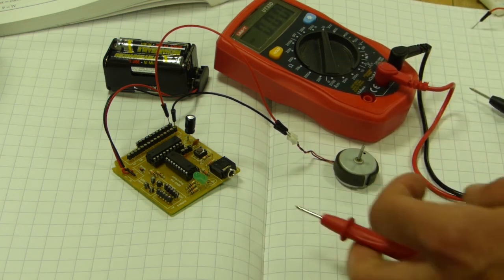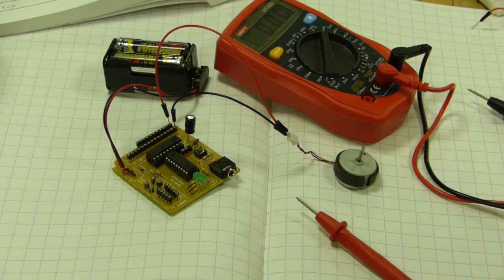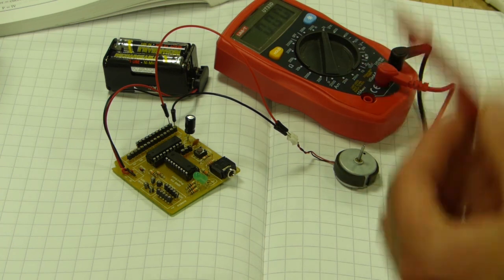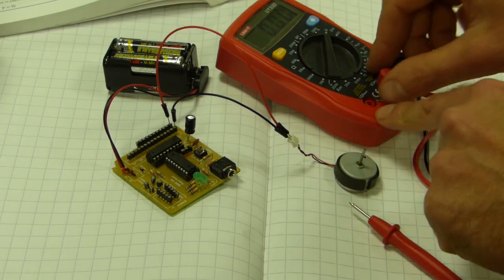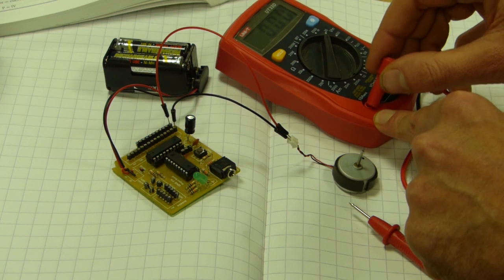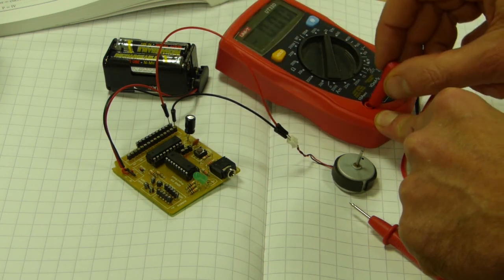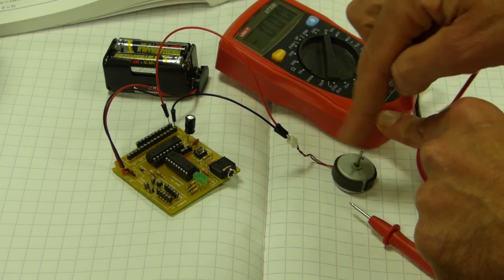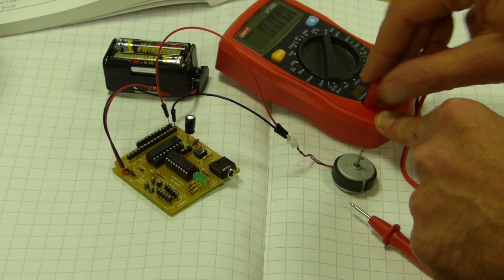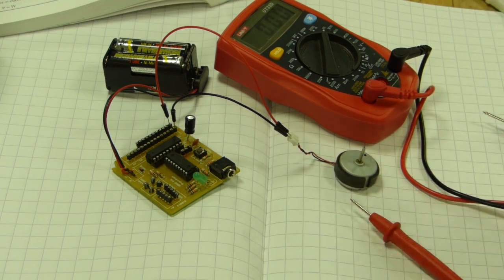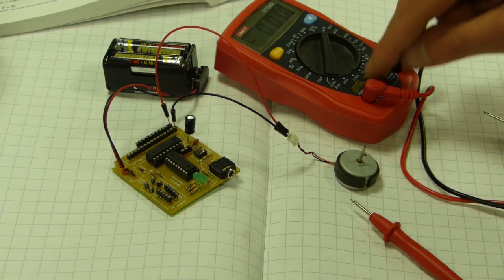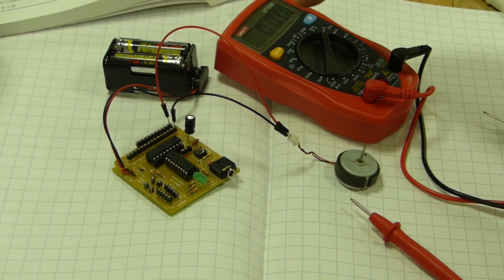It's not quite the same with current. I mentioned it in the last episode, but basically what we need to do is create part of a circuit with these wires. Now what I'm going to do here is change this plug here to 10 amps. Now just look at the warning as well. We're doing quite a small current. I'm not really worried that this motor is going to draw 10 amps. But if you are doing something that's got a slightly bigger load, you might want to just be careful not to run it too long through the meter, especially because it's not fused.